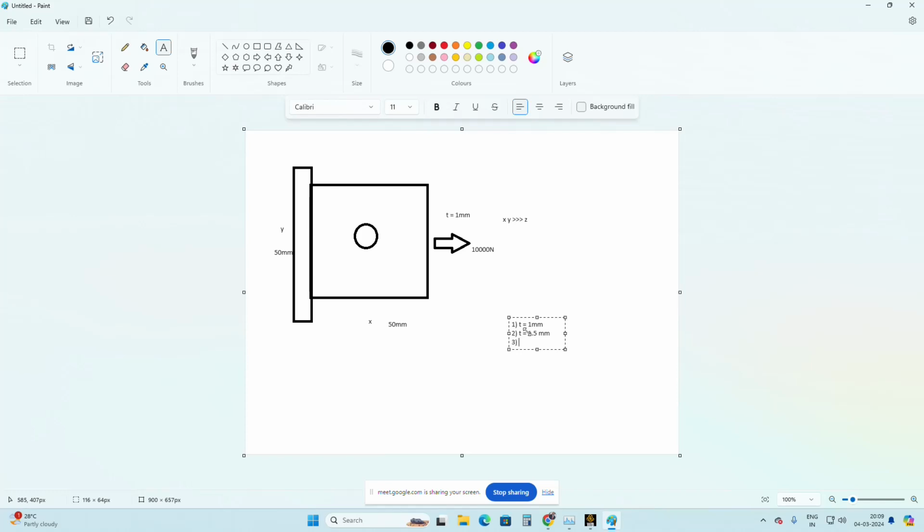Even if you take any component, like a wing structure, if the aircraft is flying at a certain altitude, it takes an air load. The air load is constant, in the sense that you can't decrease that load. If the aircraft is flying at a certain altitude or speed, based on the aerodynamic load, you can't decrease that load. Sometimes that load is maximum, and you can't change the applied load. But in order to withstand that type of load, you can alter the thickness, or add thickness to the structure.